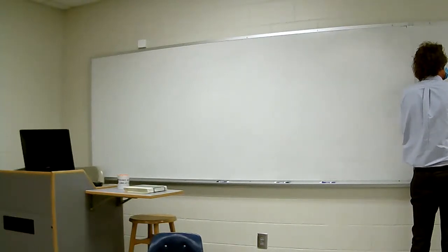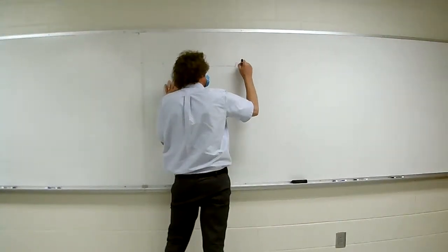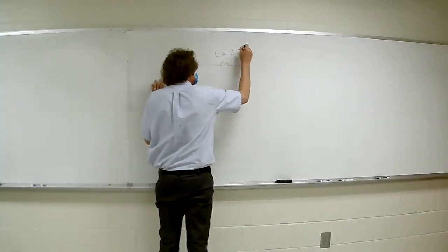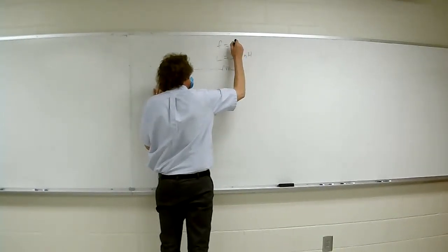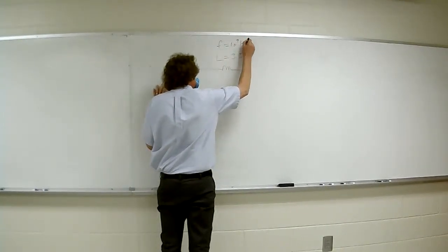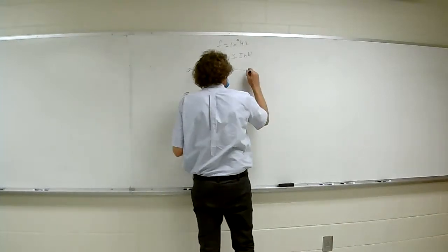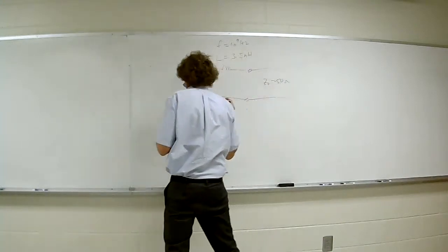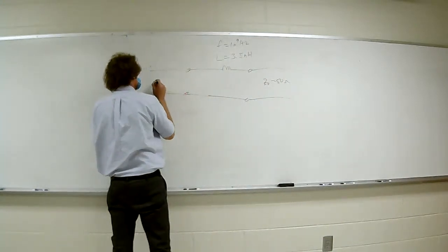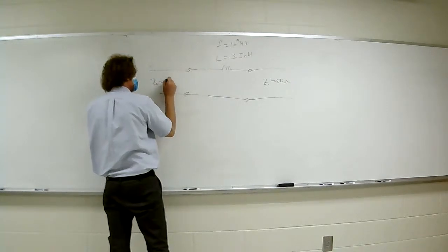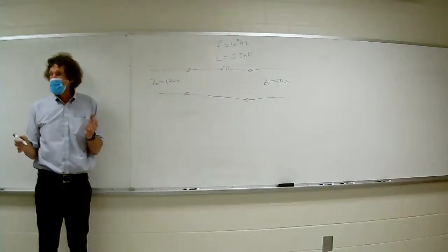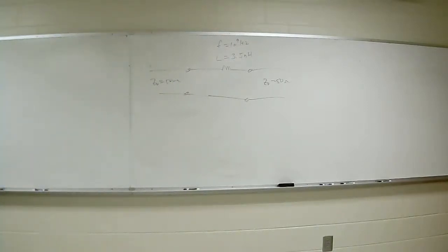So this one was a standard type thing where I had an inductor here, L, equal to 3.5 nanohenries. I had a frequency of 10 to the 9th hertz, and then transmission lines of 50 ohms on either side. And I just want the S parameters for this, right?